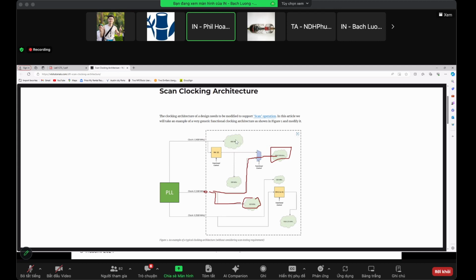It will have to trace first, and then you do exceptions. These are the default behavior, and then you do exceptions. Like I said, you can create different skew groups. If there's no talking between these two and you don't want to match them, then you say create skew group 1 here and skew group 2 here. That means if you don't create skew groups, then both of these will be matched.